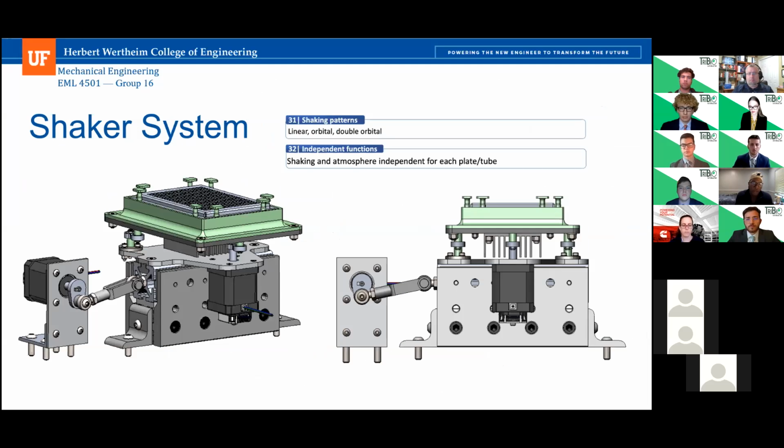Yeah, there. Okay, so is that a combination of off-the-shelf parts for that arm and cam kind of thing, or did you guys intend on making those? That's correct. So for example, the clevis is an off-the-shelf part, all the hardware off the shelf. The only things that aren't off the shelf there are the dog bones. If you see at the linear motor, there's that aluminum piece that's just 1/8" aluminum that would have to be milled out. The same thing directly under for the orbital shaking, there are also custom aluminum parts that you press flange bearings into.